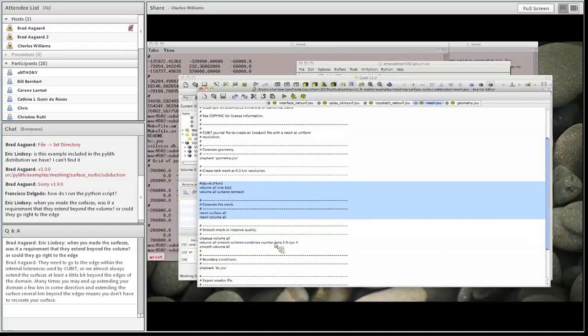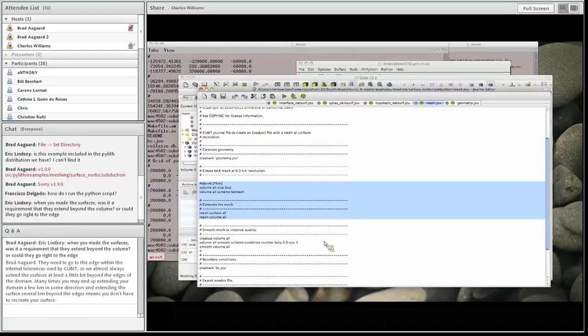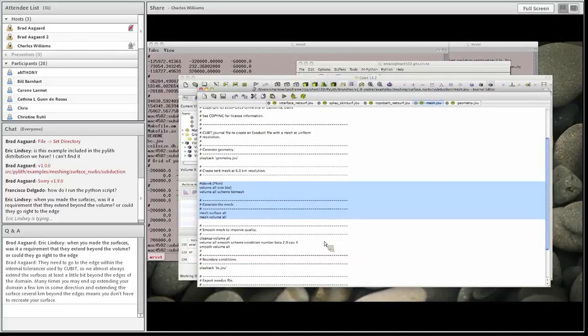So you'll loop and start with a relatively high value of beta and then reduce it by a small amount within the loop. I'm not going to do that today just because of time constraints, but you do want to, if at all possible, get your condition number so that you don't have any cells with a condition number higher than 2, and the more you can reduce it, the faster your finite element model will run. So now we're going to just quickly look at the boundary conditions.